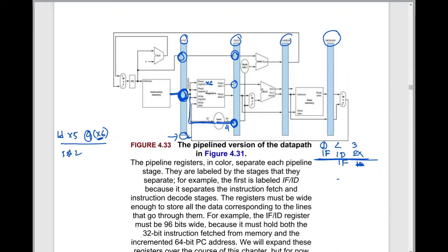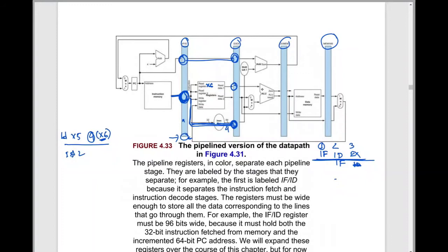That's why the value of x6 will be forwarded here, PC will need to be forwarded here, and this immediate value also needs to be forwarded. You cannot just keep it stored here. If you store it here, it will be overwritten, so that when you perform execution here, you cannot get it. The same thing here, you can see now x6, if I only go with load instruction, then x6 will